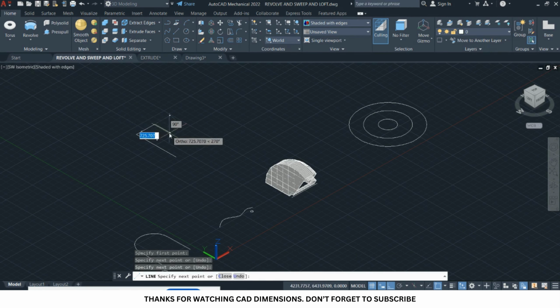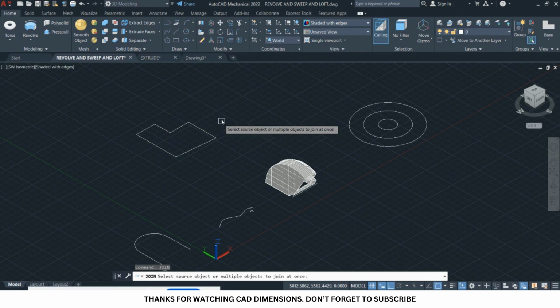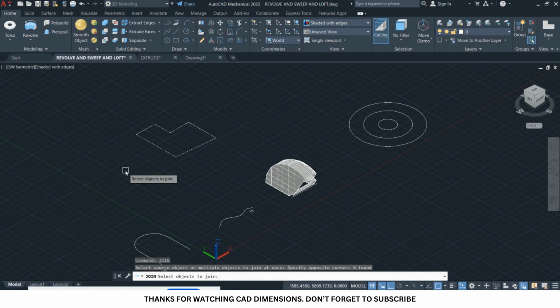Okay, so let's look at the solid I was talking about. So let's say I have a shape like this. Let me click on close to close it for me. And I want to create a revolve around this line. So first of all, let me try and join the whole shape together.